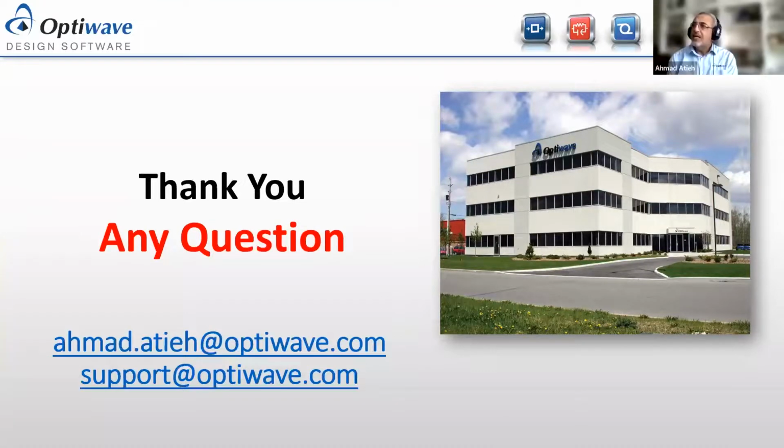Perfect, thanks. Also, any equipment basically comes with a manual which has the SCPI commands in it. You can look at these commands, test them in the OptiInstrument single command window, and make sure that they work. Then based on that, you build your sequence of commands. So it's a step-by-step process. Okay, thanks.